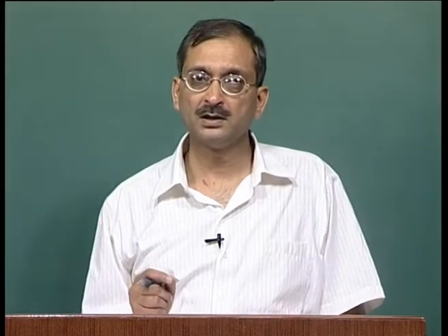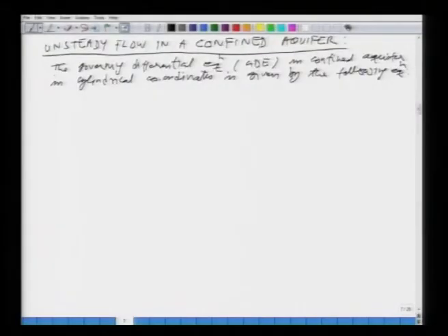So, let us look at the governing differential equation and one particular solution which is very famous and important in groundwater hydrology, proposed by Theis. So, we will look at that. First, let us see the governing differential equation, which is described as: del squared H over del r squared, we will not go into the details of the derivation of this, is equal to S by T times del H over del t. So, this is your governing differential equation.